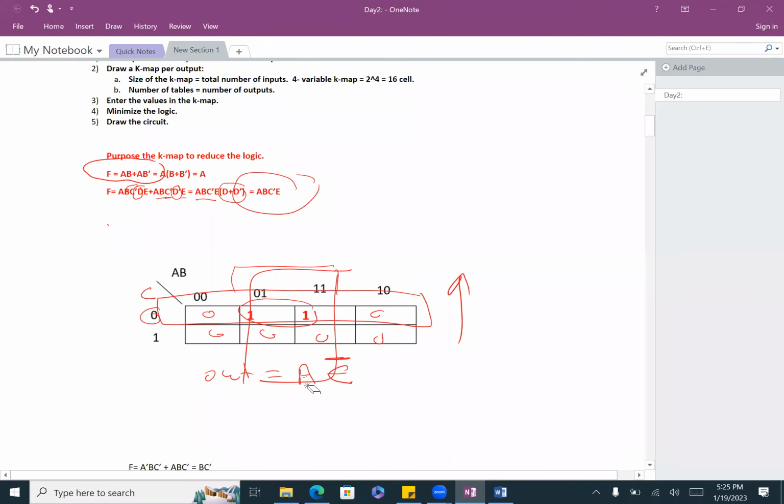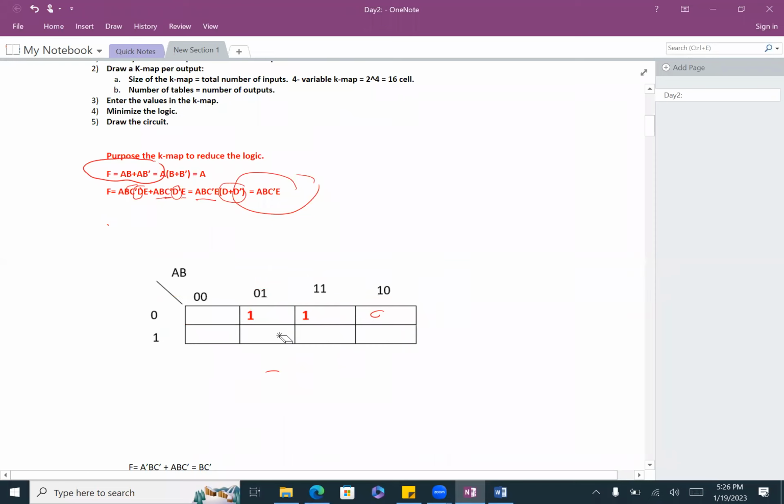Let me repeat that. That's digital design. Usually, again, when you have ones, you try to combine them, either in 2s or 4s or 8s or 16, based on the table. But since we have a small table, we have only 2. And how do you write the equation?